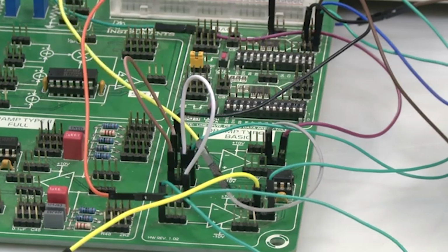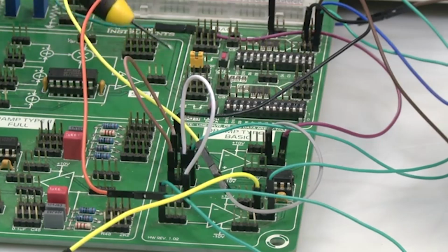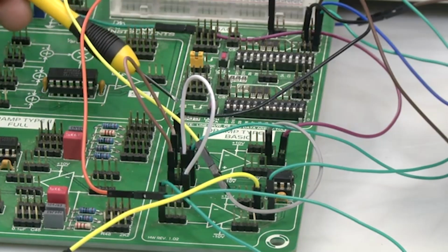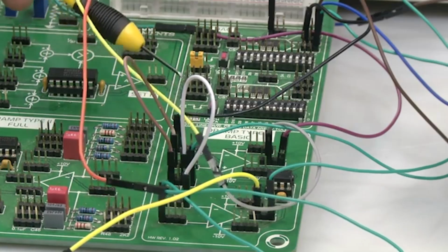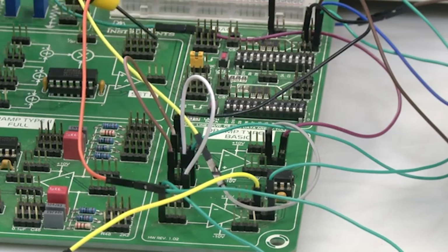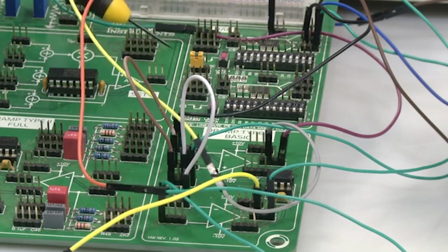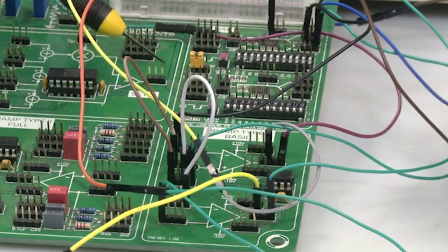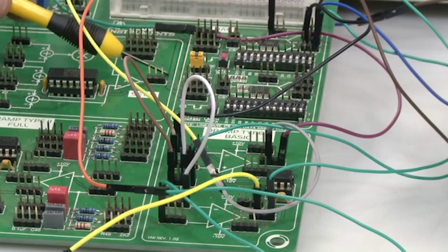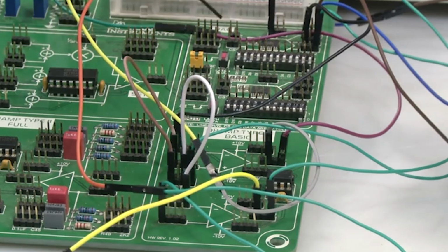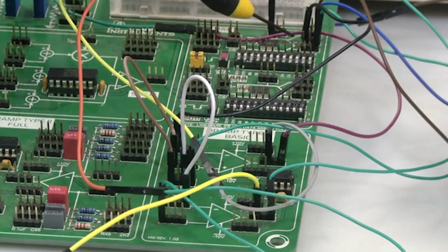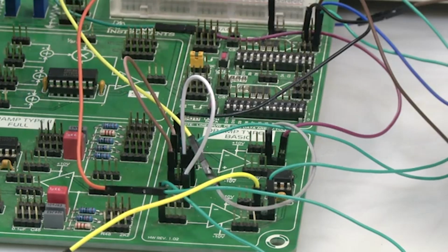So here we have the board where we have implemented what we just saw as circuit. So what did we just see? We had the DAC, and we are trying to integrate an op-amp based amplifier with the digital to analog converter, so that we will be able to control its gain digitally. That is what we are trying to see, a digitally controlled variable gain amplifier. So here, as we have seen before, this is the DAC setup, that is, the digital to analog converter setup, and we have the IOUT1, IOUT2, R feedback, everything connected, okay.